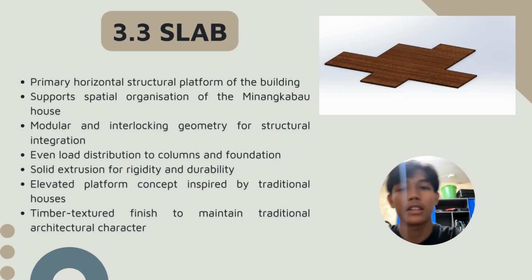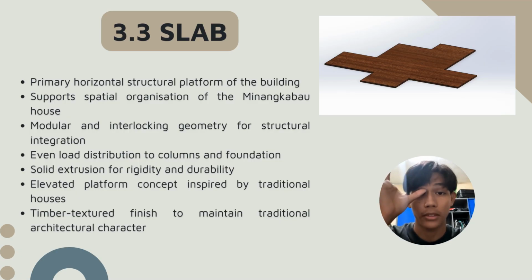The slab functions as the horizontal structural platform of the building. It supports the overall spatial layout of the Minangkabau house and distributes loads evenly to the column and foundation. The slab is designed in a modular and interlocking form, which improves structural stability and integration between components.